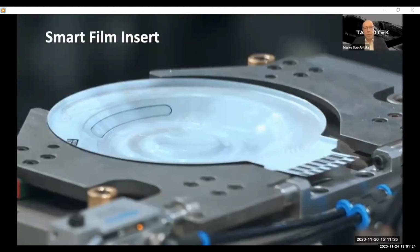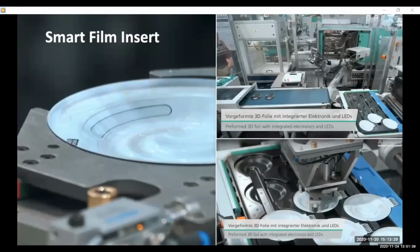The term insert being used as feeding into a tool is not from a feeder. Typically, it is by the robot. And that's why the film will be placed into a tool as an insert. Due to the sensitivity of electrical components, printed sensors, traces, and LEDs, it is important to consider proper part handling to avoid part handling related defects.